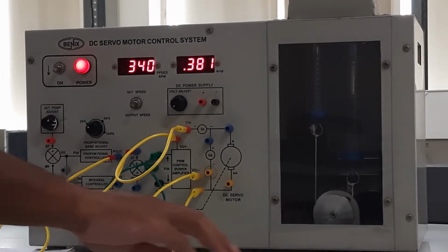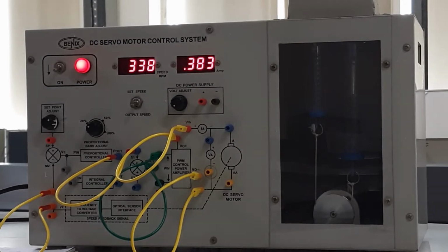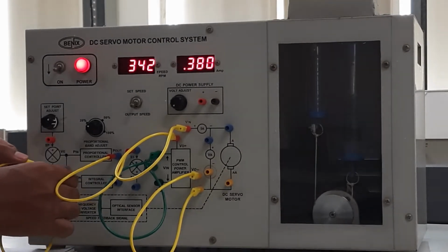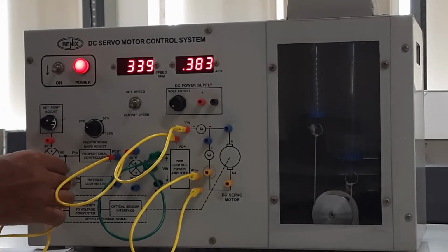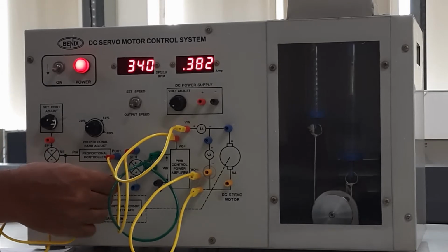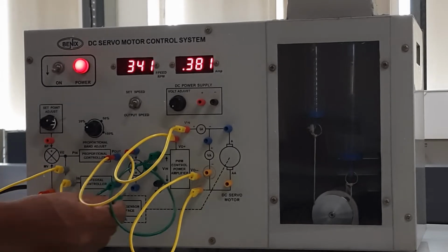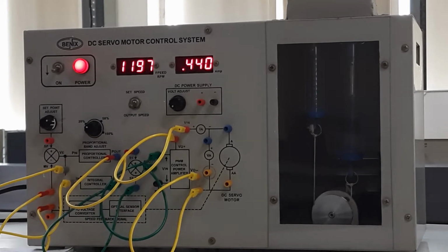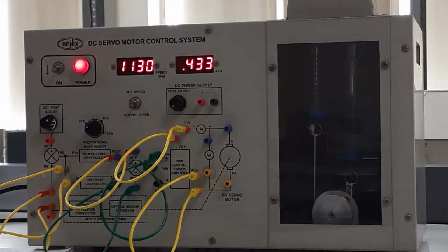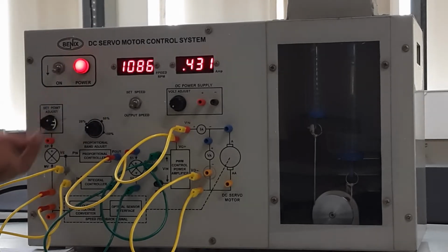Okay. Now I am going to use a PI controller. For using a PI controller, all I am going to do is connect this PI into this system, and then I am also connecting it to this particular system. Now you could see the speed has changed to 1150, and then it will take some time. The feedback loop is taking some time, and this speed will settle down at 1000 RPM. We have to wait for some time.